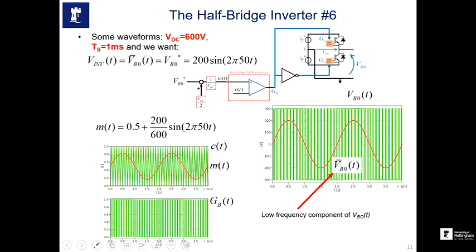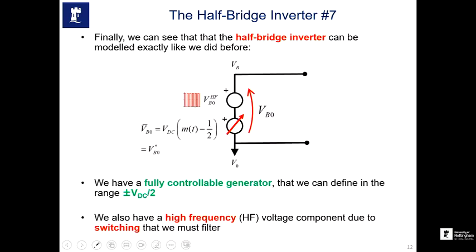So if you look at the circuit, depending on what sort of current you inject in here, because this is in the middle of the DC link, depending on the current injection and the current path, the two voltages which we need to be equal, we need VDC by 2 and VDC by 2 for both top and bottom sources. But depending on the current flowing in the circuit, there could be imbalance, because normally we stabilize this DC link using capacitors, and the capacitor charges and discharges depending on what sort of current you are injecting here. That can cause problems.